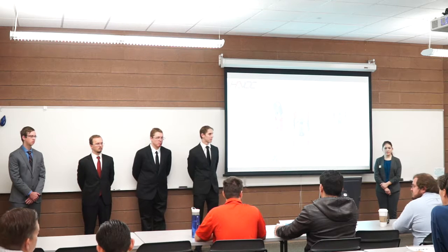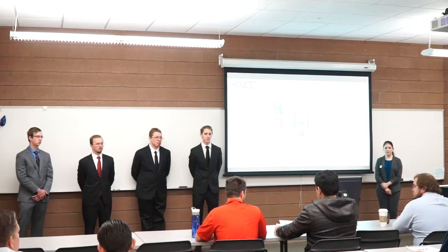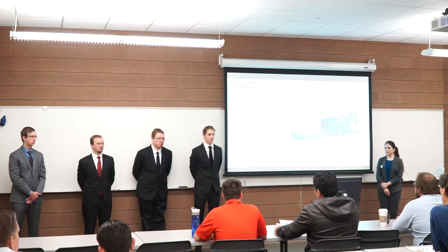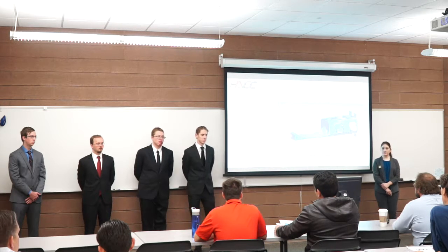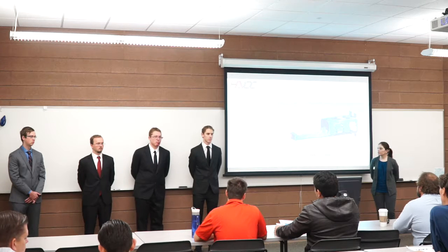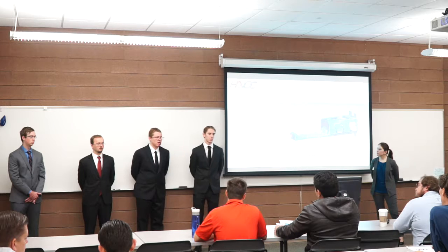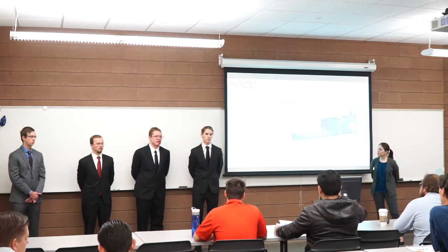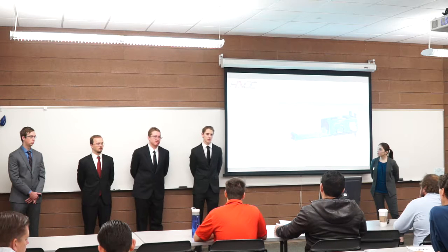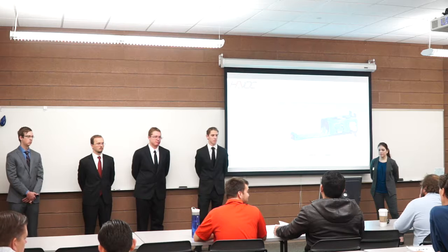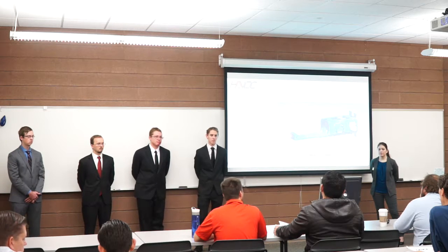Okay, so I do want to point something out. Slide 21. For your stress analysis, you mentioned the factor of safety. So you calculated your margin to ultimate. What's your margin to yield? The specific data sheet we had for the material did not have the specific yield. Okay, that's going to be pretty important because you're dealing with plastic.